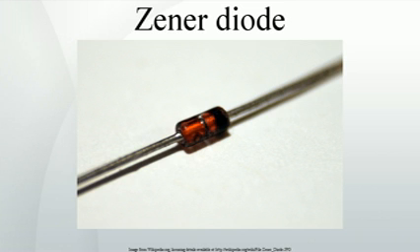An alternative, which is used for voltage references that need to be highly stable over long periods of time, is to use a Zener diode with a temperature coefficient of plus 2 mV/°C, breakdown voltage 6.2-6.3 V, connected in series with a forward-biased silicon diode, or a transistor BE junction, manufactured on the same chip. The forward-biased diode has a temperature coefficient of minus 2 mV/°C, causing the TCs to cancel out.